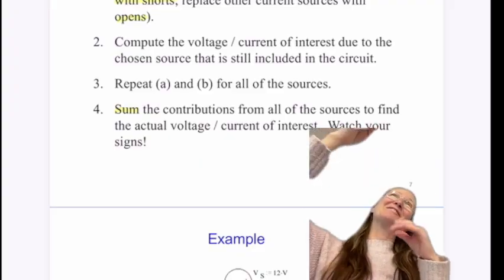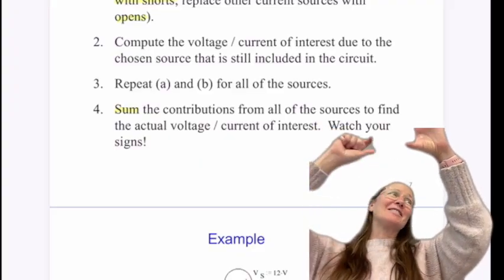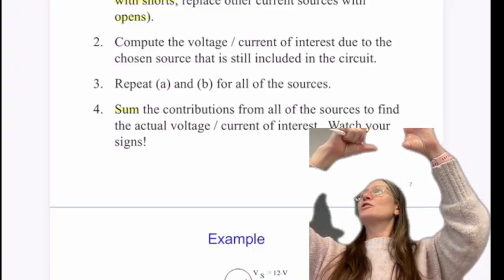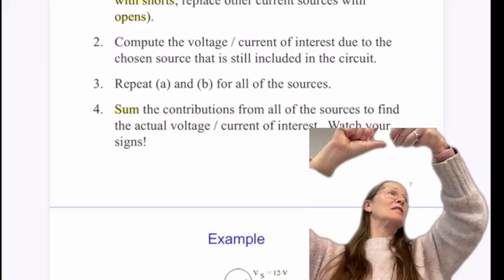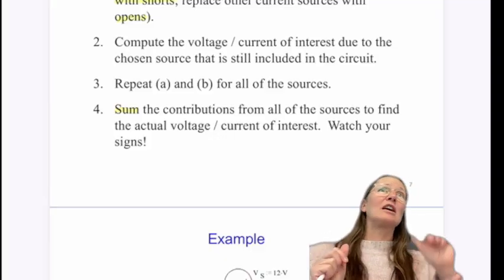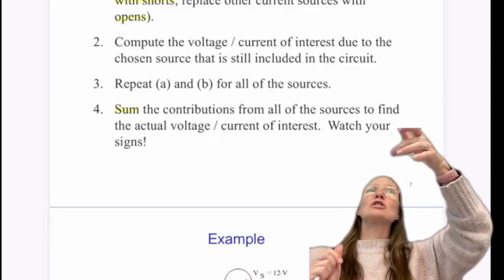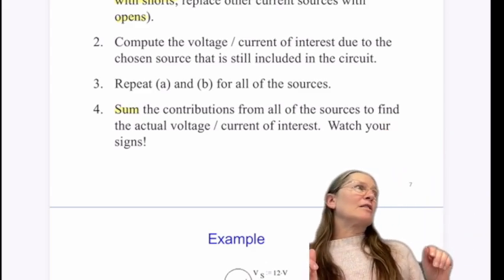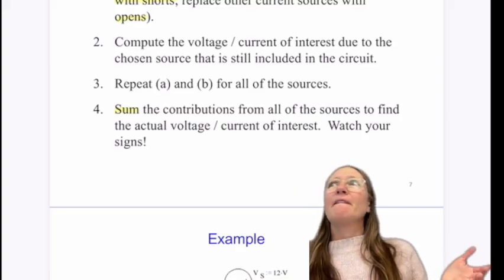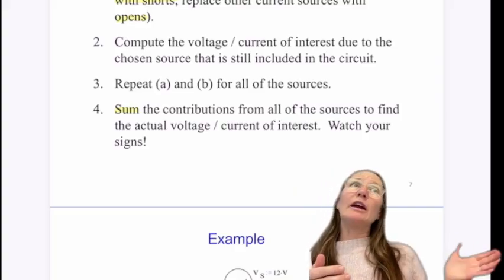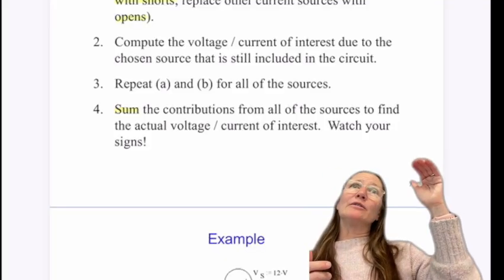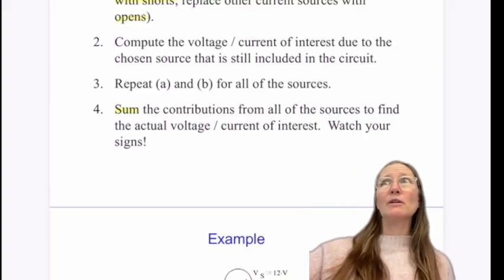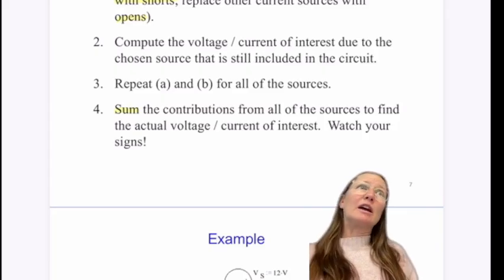okay, so maybe I should reword this. Okay, if I have a plus and a minus here and I measure across this a negative, what does that mean? Correct, the direction, it's just meaning the battery is basically in a different direction than I think. So it's a location of the voltage. So current being negative, what does that mean? Correct, it's just going the other way than what I labeled it in the circuit. Okay, so again, negatives for us mean a different thing. So we're going to see in a minute with op amps that a negative again means something else.